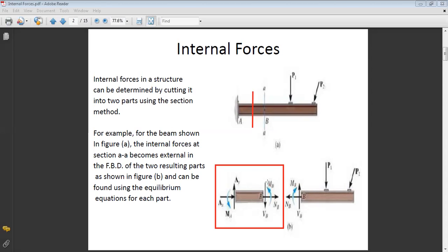So always we put a V in a way to rotate clockwise about the end of the beam. So here, if you look at your figure, you have that the shear is downward. Why? Because look, always the shear force, which is in the plane of the section, should rotate in the clockwise direction about the extremity of the cut. Okay?